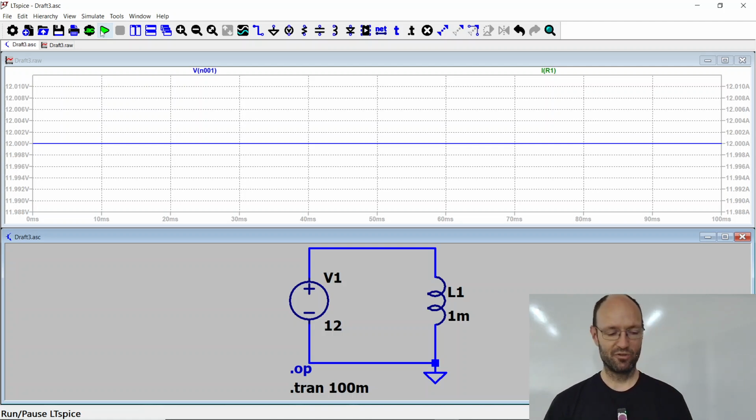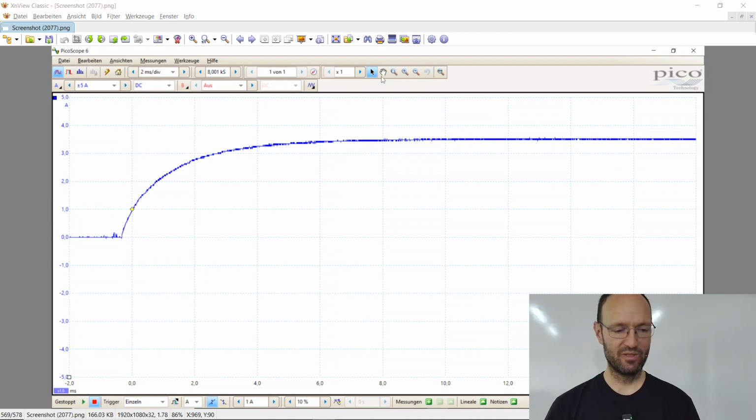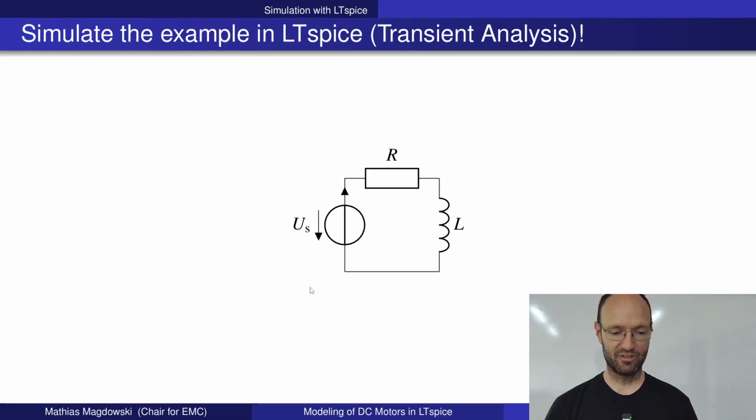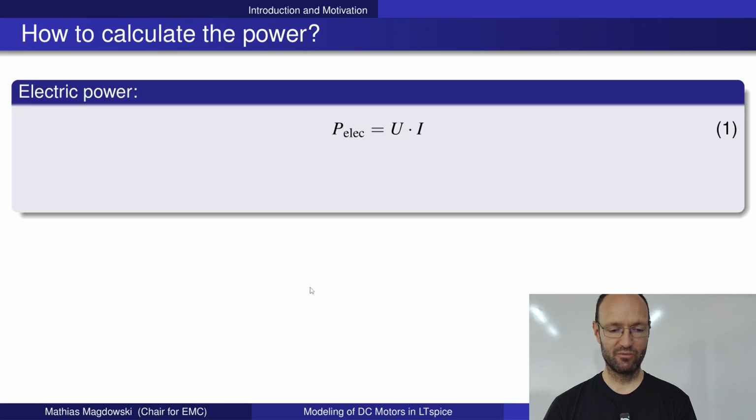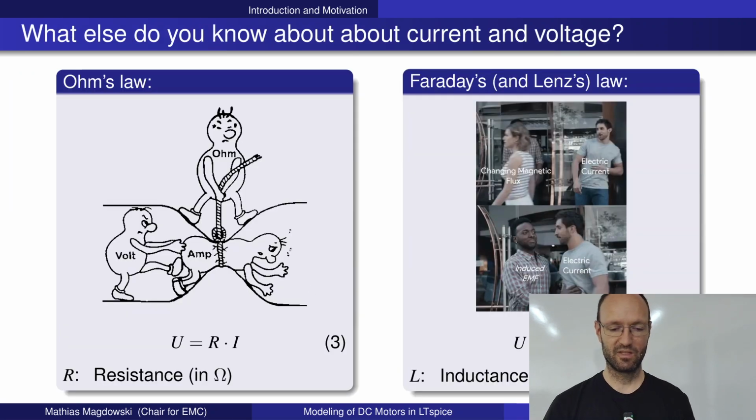Yeah, it should, because if you remember what we discussed on Wednesday, also for the inductor, I need to go way back in my slides, somewhere to the beginning where we discussed the inductance. Yeah, so we have a constant voltage, we have a constant inductance, then we should get a constant time derivative of the current. So the current should just increase linearly up to infinity. If we wait infinitely long, current should go to infinity.